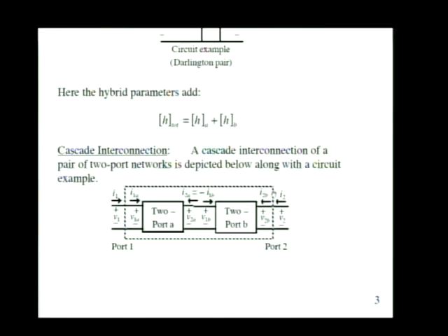And it's easiest if you can absorb that minus sign into the definition of the ABCD parameters, so that when you find, let's say, I1 and V1, you're actually finding it in terms of the current flowing into the next two-port and the voltage across the terminals of the next two-port, the negative of the current that we normally define at port 2 of the first two-port.